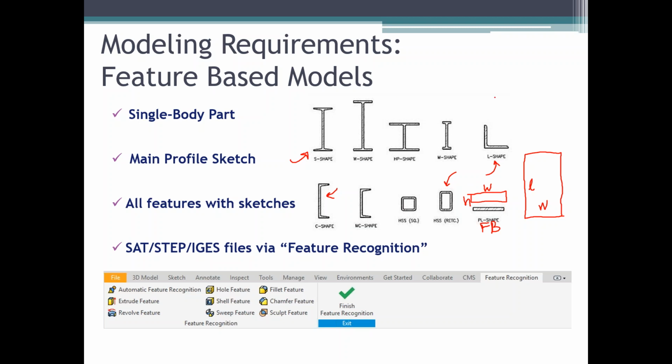Okay, so that's all about your Inventor area. So what happens if you're receiving any files from your third-party platform? Most of them are DSTV files, IGS files, SAT files, right? We can work on those, but it's via a tool in Inventor called feature recognition. Anyone who has a valid Inventor subscription can go to the Autodesk App Store and download it from there. And it's very easy to use. I'm going to show you a couple of examples in my coming presentation.